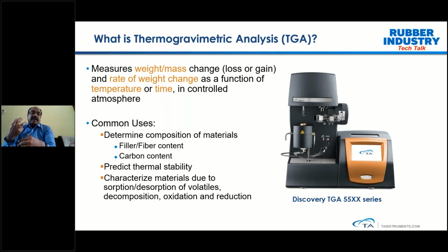Obviously, the moisture which is present in the polymer can affect your performance. So TGA is a technique that can clearly quantify how much moisture is present. In the case of an unreactive monomer which is present as a solvent, you can also use TGA as a technique to quantify how much solvent content is inside the samples.